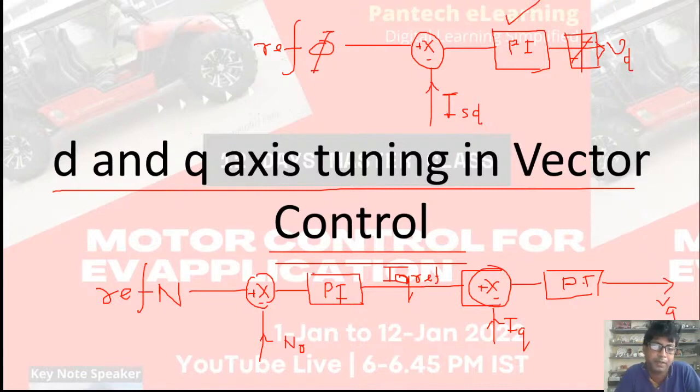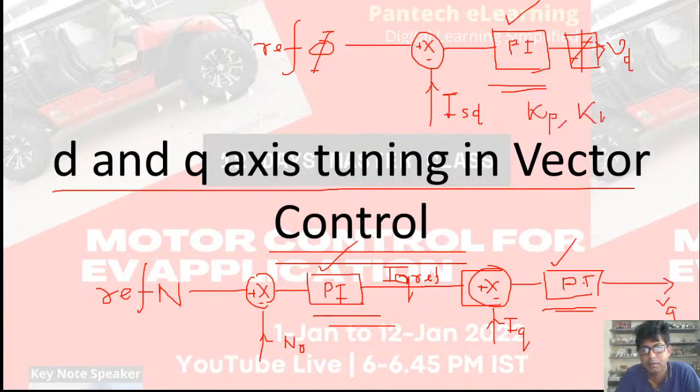So these 3 PIs: this is the direct axis compensator. This is the quadrature axis outer compensator. This is the quadrature axis inner compensator. So this is for flux regulation. This is for torque regulation, and this is for speed regulation. So we will be knowing how to set this Kp and Ki.